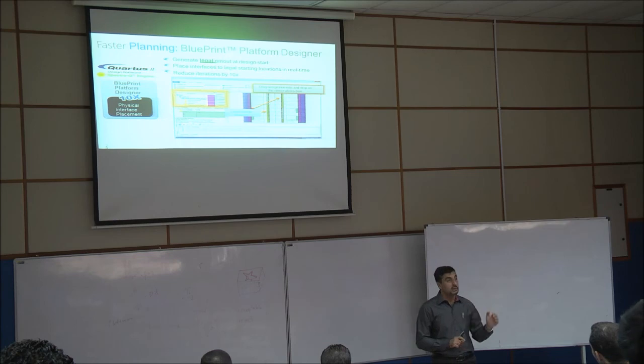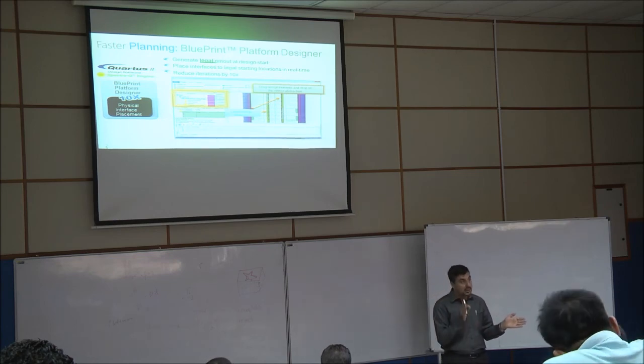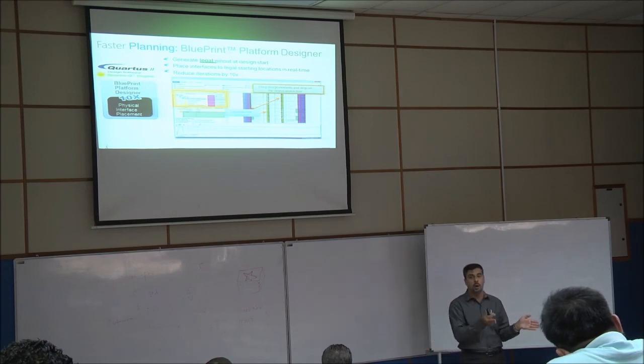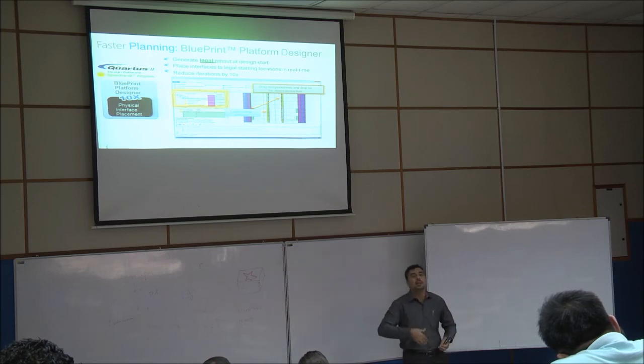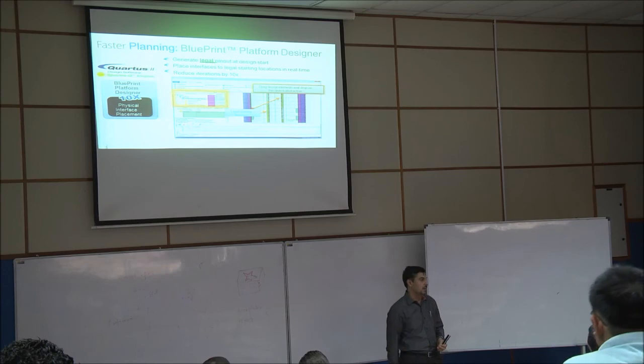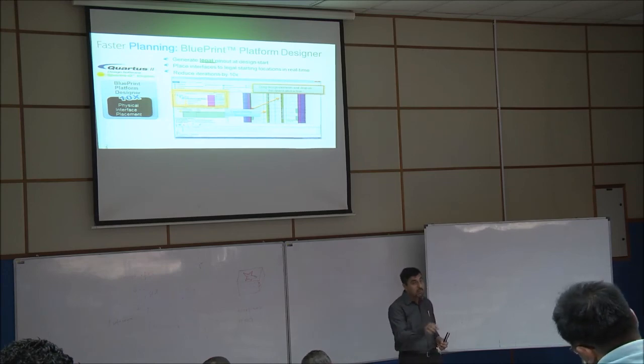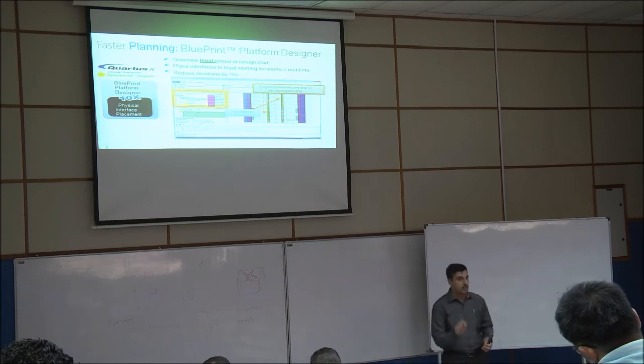Why? Because theoretically you can use 50K. Practically, due to the routing problem, because at the end, the logic element is not the only problem. The other problem is the routing. Logic elements are enough, but routing later on will add delay to your design. And I'll show you how they overcome this problem in the new Stratix 10.